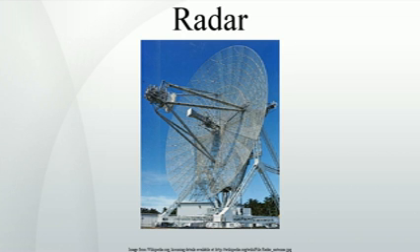As an example, moving target indication can interact with Doppler to produce signal cancellation at certain radial velocities, which degrades performance. Sea-based radar systems, semi-active radar homing, weather radar, military aircraft, and radar astronomy rely on the Doppler effect to enhance performance. This produces information about target velocity during the detection process. This also allows small objects to be detected in an environment containing much larger nearby slow-moving objects.